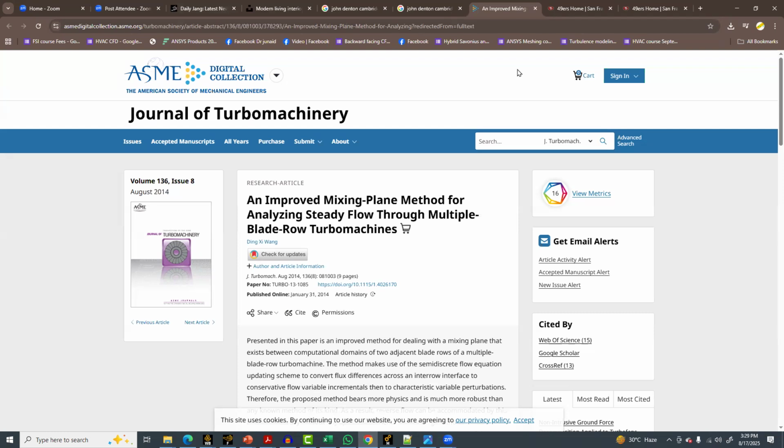So for example, if we are working on a compressor, first will be the rotor, then we have the stator. In centrifugal compressors, we have the centrifugal impeller, and then we have the fixed plates or guide vanes, whether the guided diffuser is there or without guide vanes. That is called the bladed diffuser or the vaneless diffuser. So let's say this is the rotor here, and then we have the stator here. This is circular. If you take a look from the front view, it is this way: hub and then the blades.